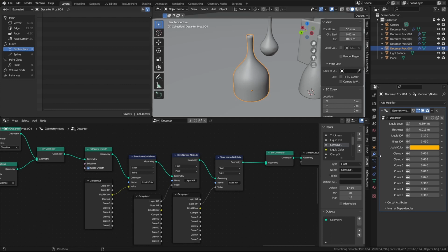The one thing I spent a lot of time on is allowing the shape of the glass to be controlled from these nodes. So there are 6 values that correspond to 6 locations along the curve, which, because the edge is defined by a NURBS curve, is actually plenty. You could add more. The more you add, the more control you get, but also the more tedious it is to get to exactly the right shape. Like if you had 100 controls here, you'd have to move 100 little sliders and get each one just perfect.